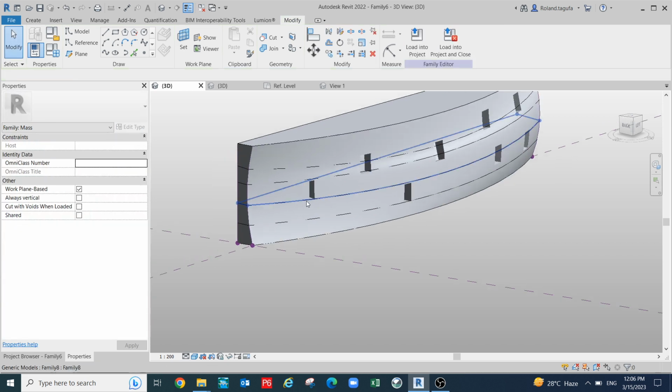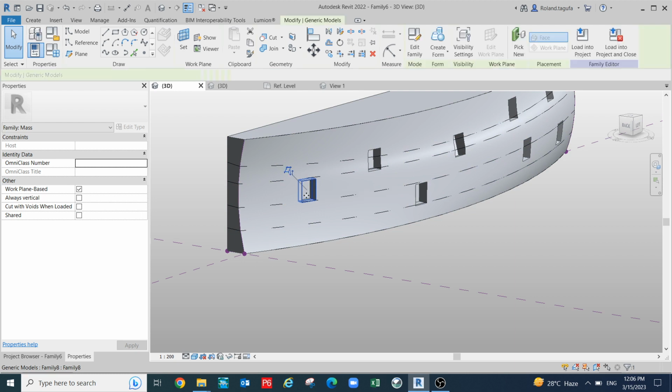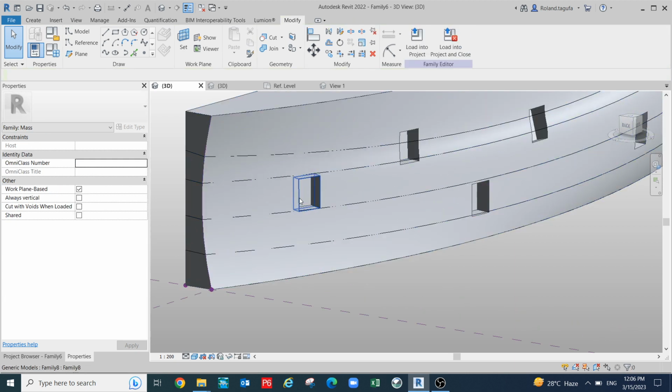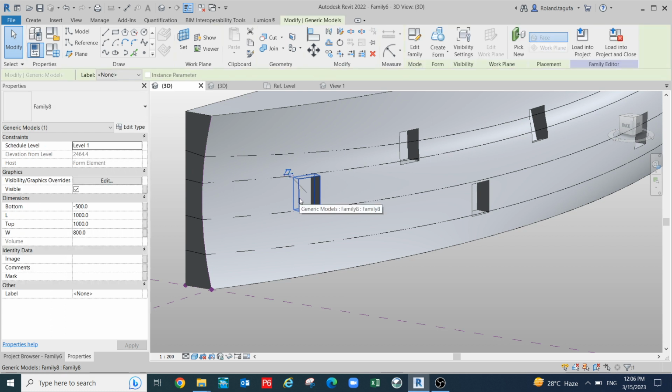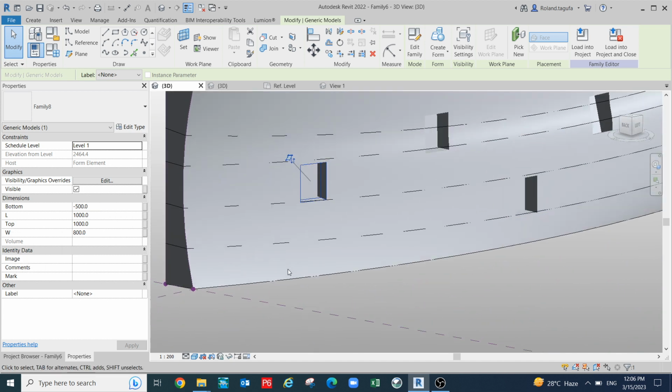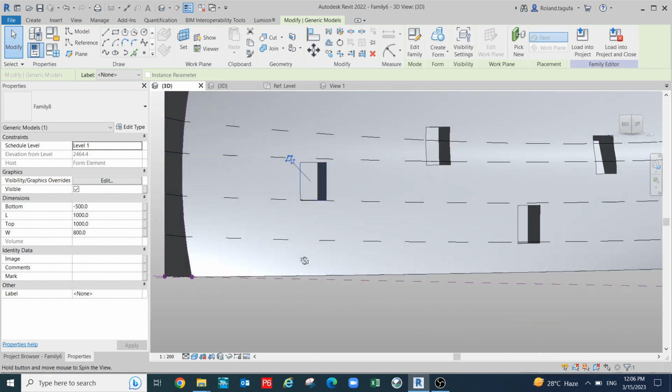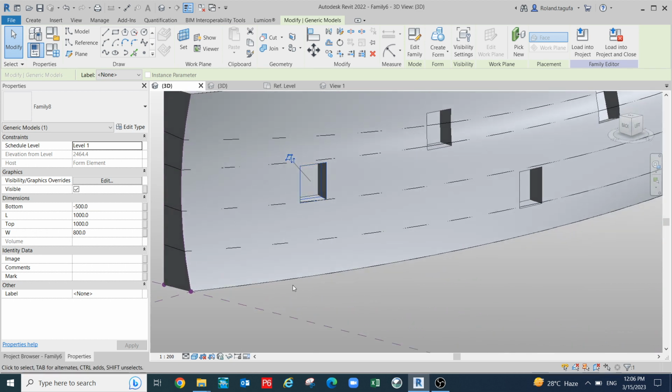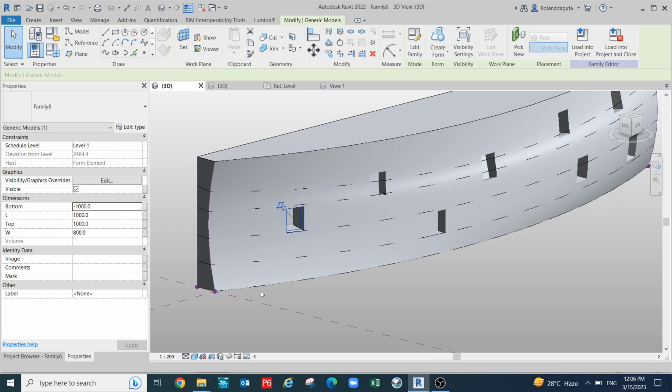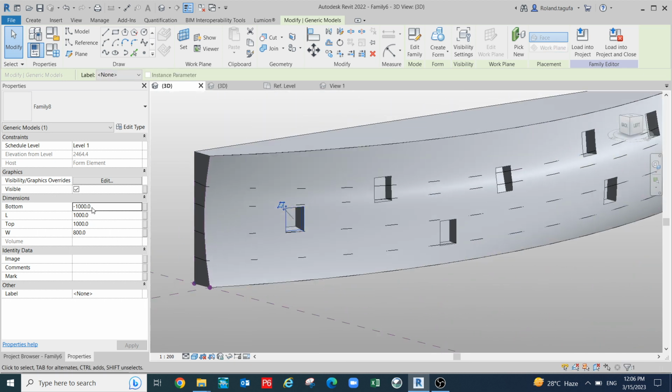And then since this is an instance, you can edit this one by one. You just click this window, and then you can see top, bottom. This is not traversing there, up, back. You cannot see the window. If you want to see this open through and through, you just select your negative extrusion into maybe 1000. Apply. Make it more.